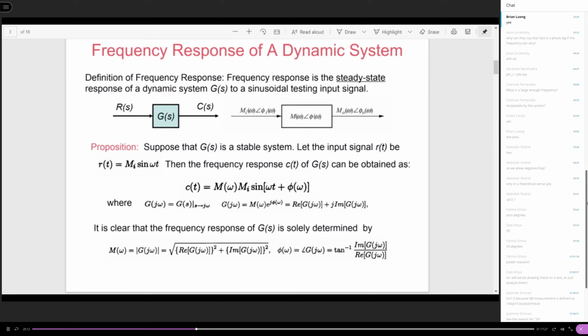But if you use a certain periodic triangular wave, even if you conduct the Fourier series decomposition, if you recall the math, the frequencies in the Fourier series are always discrete, not continuous. In other words, it can only include certain discrete values of the frequency in the spectrum, not the continuous spectrum.